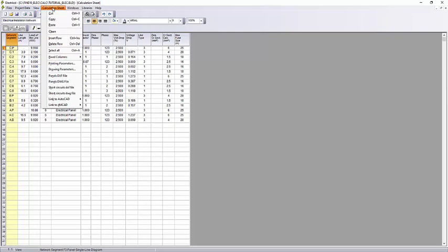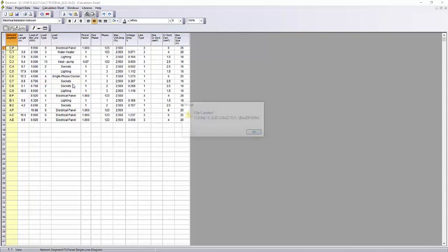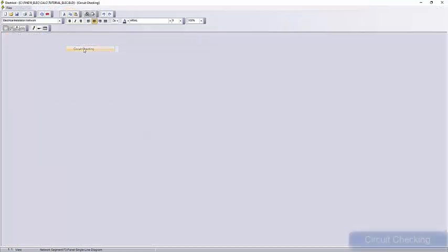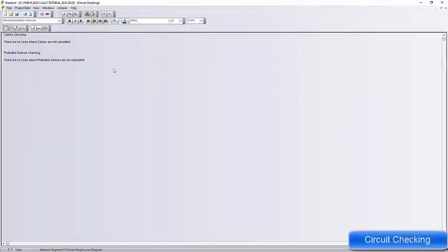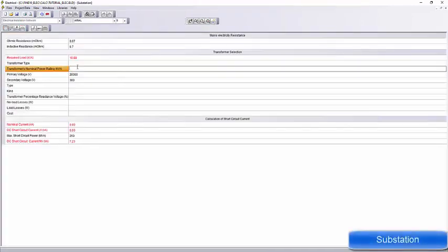From the calculation sheet, we can export the panel and short circuit segments to DWG or link them automatically to AutoCAD or 4M CAD. This option checks every line of the circuit about its cable cross-section and fuse. If the program cannot calculate for any reason these two parameters, there is a warning for the user in this window.